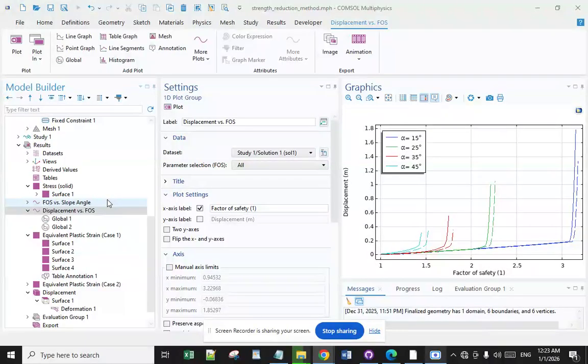The results indicate that both the limit equilibrium method and the traditional finite element strength reduction method tend to overestimate the stability of intricate slopes compared with the method proposed in this study. This parallel comparison serves to validate the accuracy of the double strength reduction method proposed in the present study. Further, based on the proposed method, the relationship between slope stability and slope displacement is established, which provides a theoretical basis for the safety assessment of slope engineering.